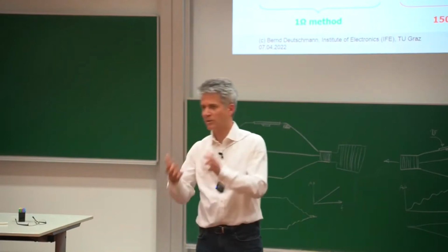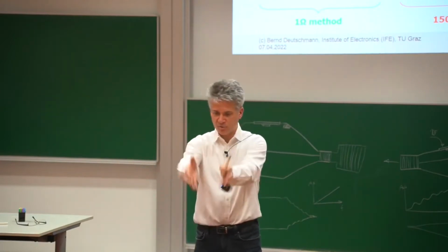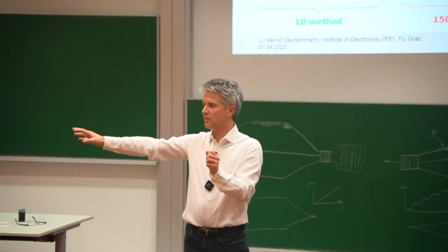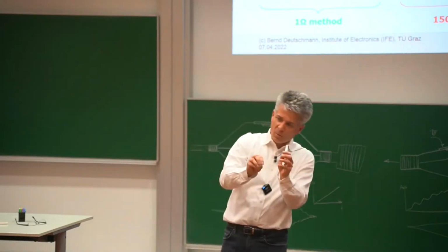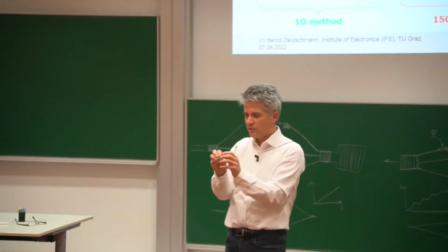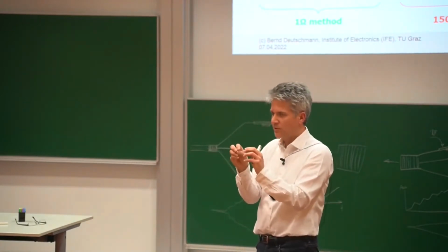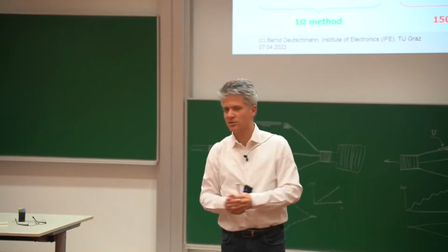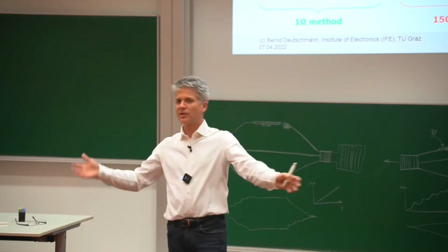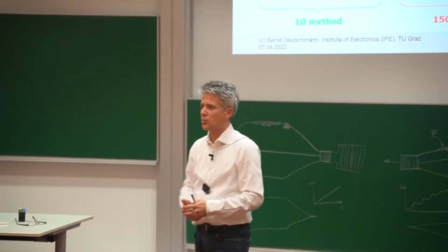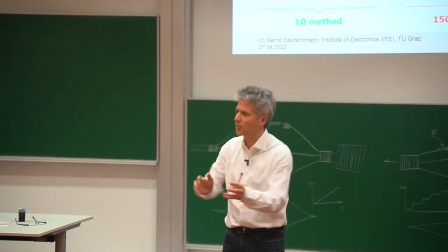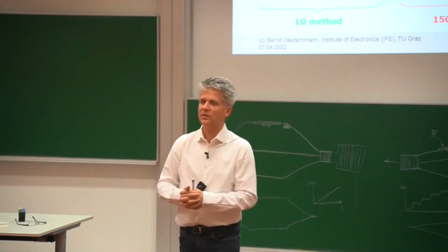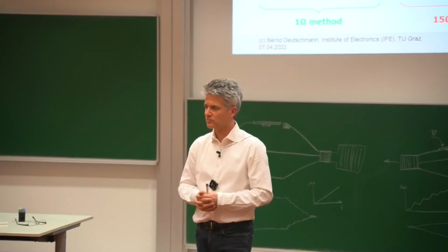When it's used, for example, in the automotive environment, I have a control unit, there is an IC in the control unit, and at the control unit there is a cable harness. So what is the impedance that the IC sees when it looks into the cable harness? They made quite a lot of investigations, and they figured out that the typical antenna impedance is about 150 ohm. Not exactly 150 ohm at all frequency ranges, but on average, it's somehow 150 ohm.